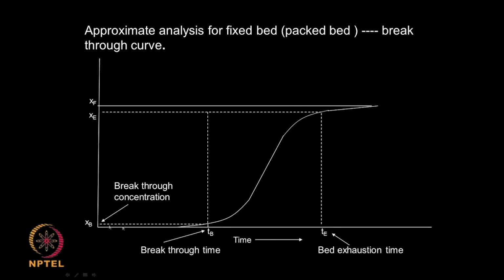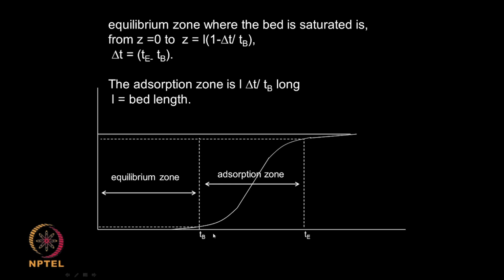The breakthrough curve is very important, because you have to stop your adsorption as soon as you see some solute coming out, and then you may have to recharge your tubular adsorber, either by putting in fresh adsorbent or by activating it by passing some chemical through it. So this breakthrough curve is very important, and the breakthrough time is also very important. So, there are some relationships.